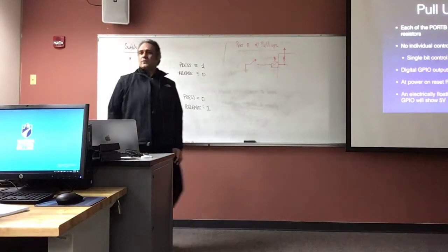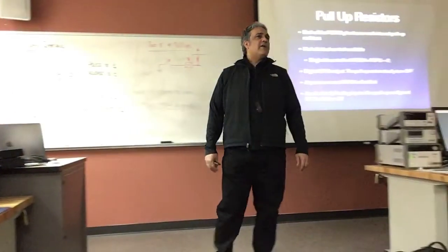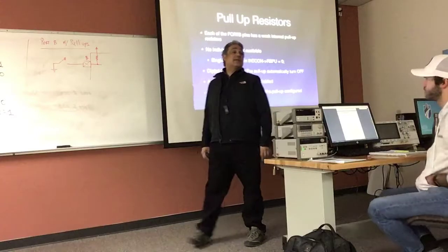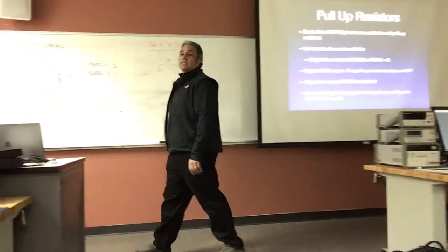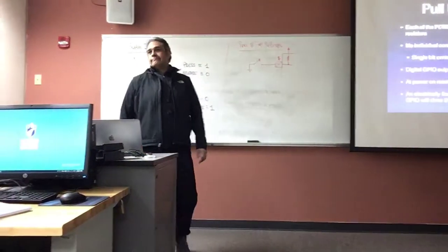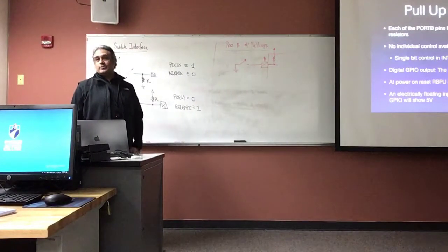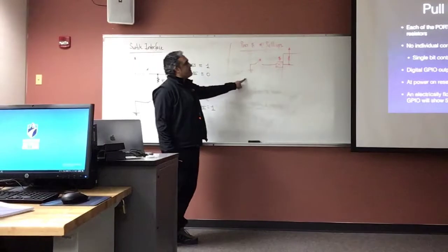Why is this useful? Well, I save incredibly in parts. If I have 2 push buttons and I'm pumping out 10 million units, it makes sense right away. It's way less parts, it's simple to manipulate, and so I know already that I have my pull-up resistors.